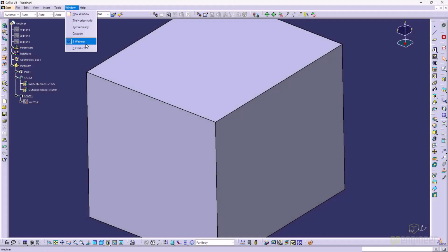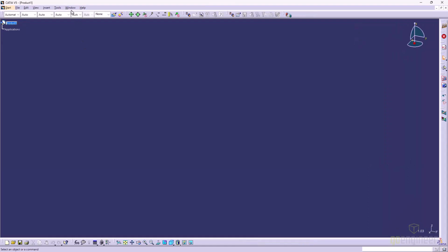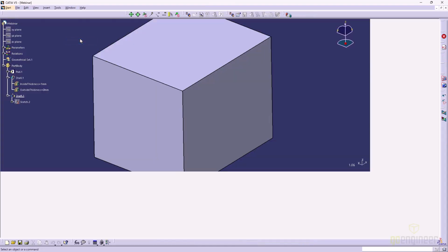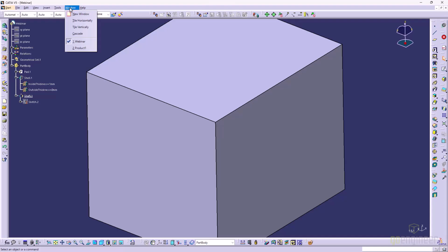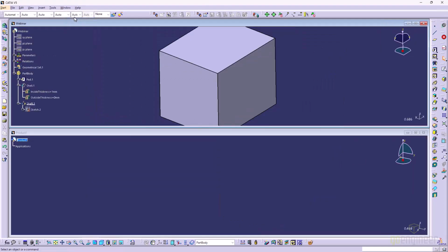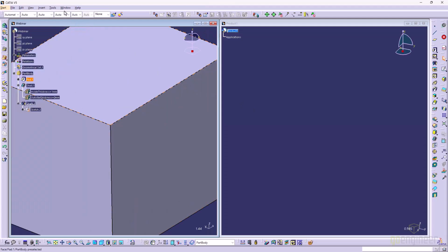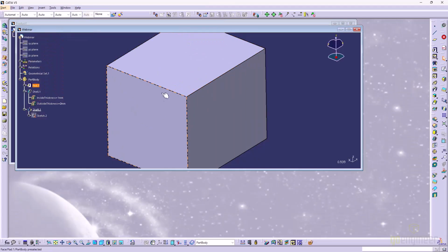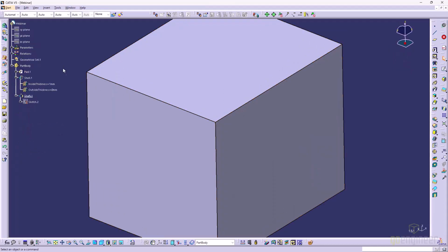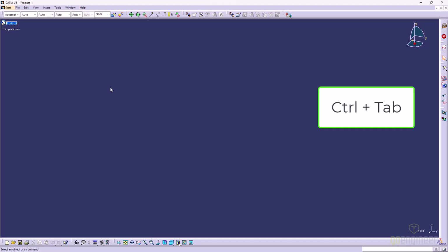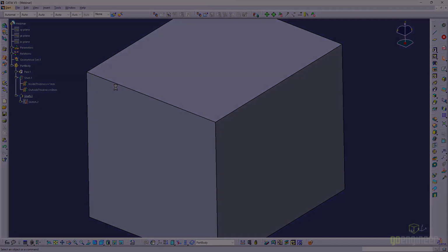The Window menu option is how CATIA users can switch between parts, products, and drawings. Within this menu, there is Tile Horizontally, Vertically, and Cascade, which position the active windows in different positions. This is useful when switching between parts or getting information from one and going to the other. To quickly switch between windows, you can use the Control-Tab hotkey and flip between your open windows.